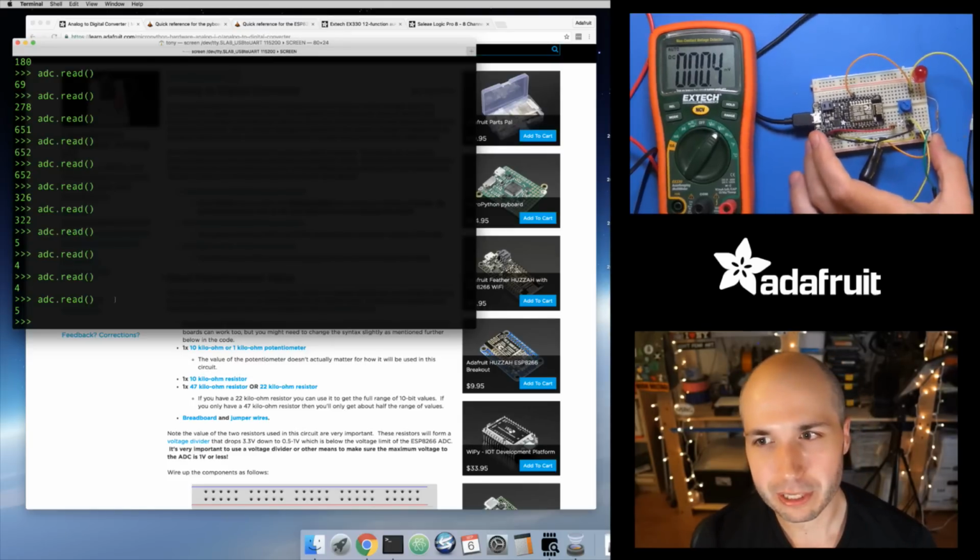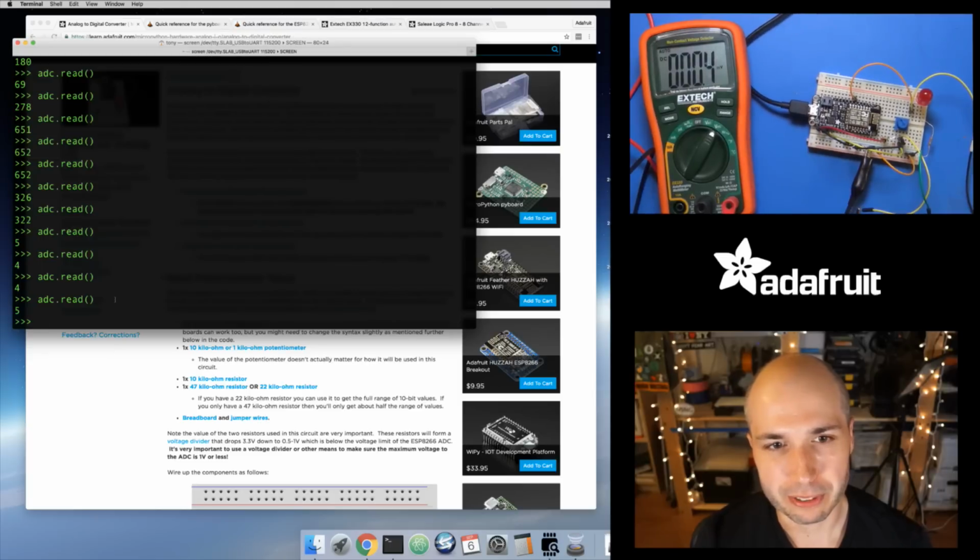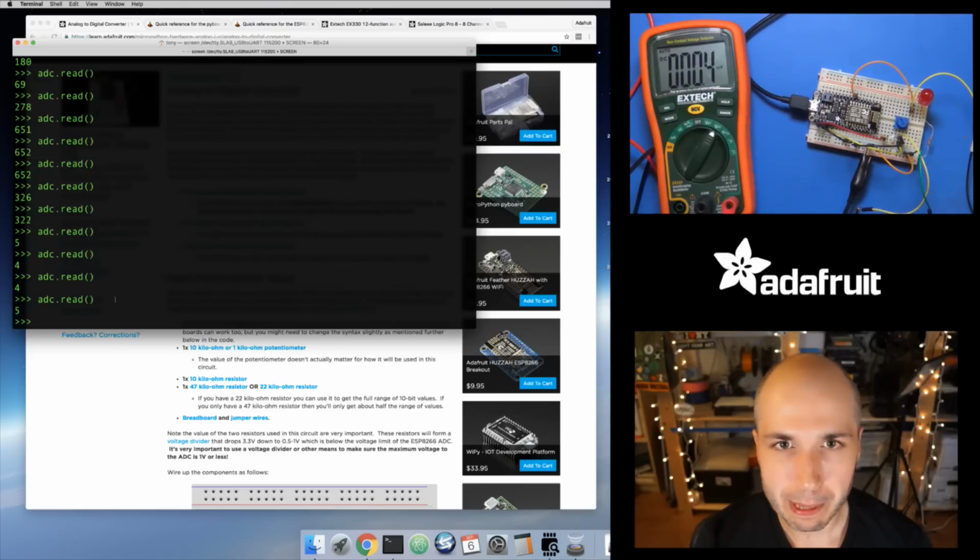One really nice thing that a lot of people will do in a project is, if it's a battery powered project and you're curious what your battery level is, you can take your battery voltage and just feed that into an analog to digital converter and then read that in your program to see, okay, my battery voltage is like 3.7 volts, so it's fully charged up, or maybe it's fallen down to like 1.8 volts and now it's out. So it's kind of nice that you can do simple things with that.